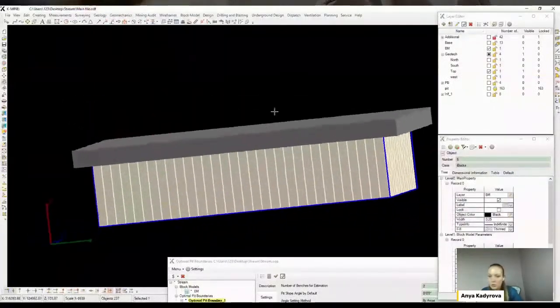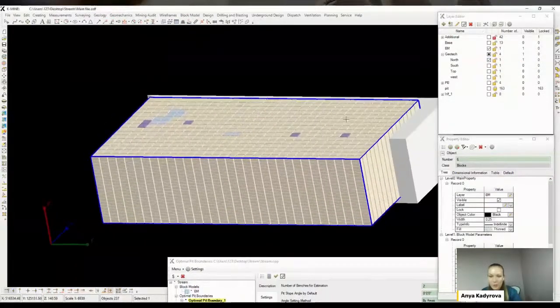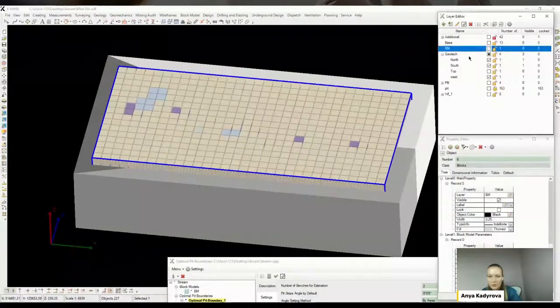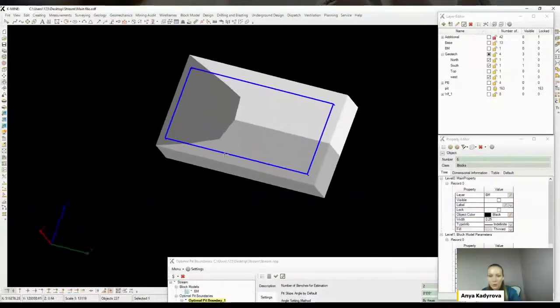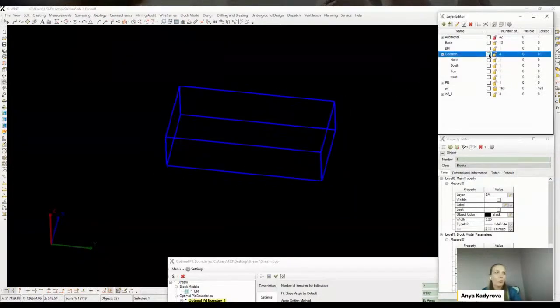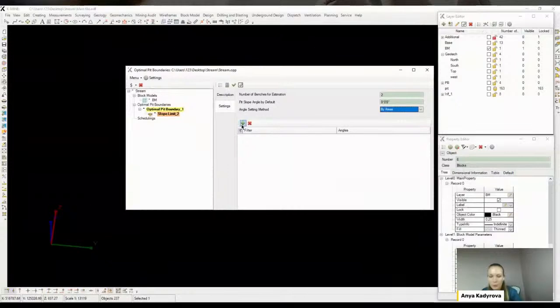So let's move on to completing the project. We will add 4 zones for each frame, and we will use a filter that we prepared in advance. This filter specifies each specific wireframe for each individual case. So we are setting north at 45 degrees, south at 40 degrees, the overburden at 32 degrees, and for the rocks of the western side of the pit, 43 degrees.